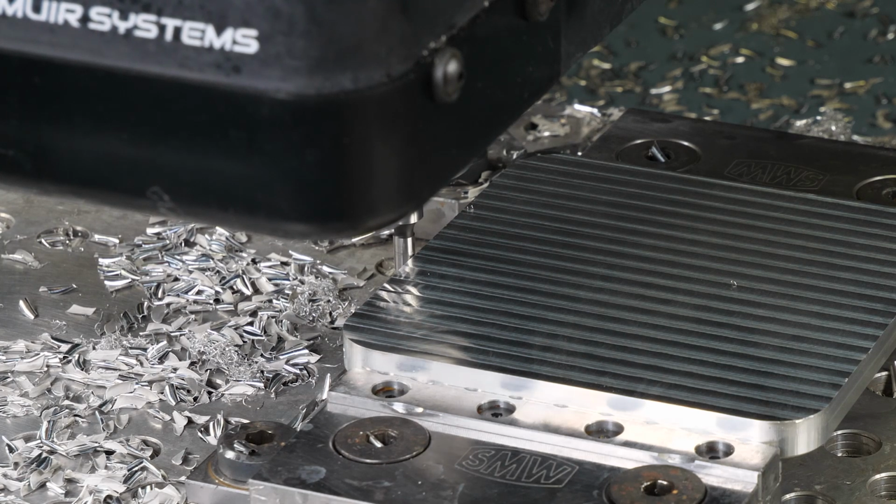See that? See how the wobble's gone down a lot? I'm going to start stepping it in. I was just stepping it at 10 thou increments. Now I'm down to 1 thou increments. So we're going to start stepping it until that. Now it might not pick it up on camera very well, but that is what you're looking out for. Certainly edge finding takes some practice to get used to, but you'll know when the edge finder snaps off.